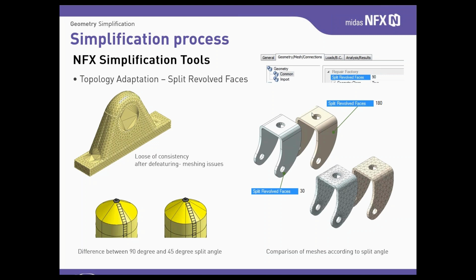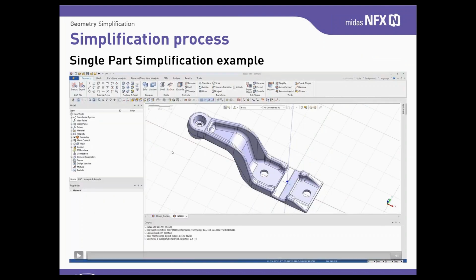As you have seen, it's recommended to check geometry by doing simple meshing before you proceed with advanced simplification, because one of the issues can be actually information lost about circular faces. So please use this feature carefully. This will determine the rest of our job. So this is pretty much an important option. Actually, it is hidden inside options.